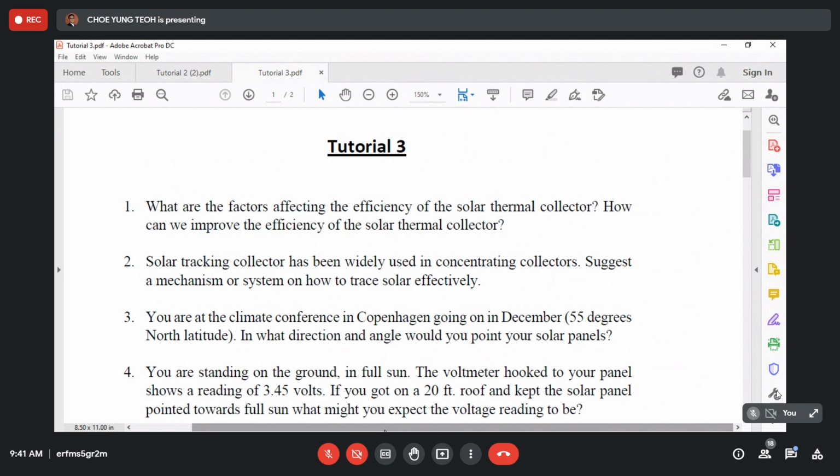But in terms of use in the evacuated tube, methanol is a very good idea. Okay, because it can change phase very fast at the lower temperature, which will carry the heat to the heat exchanger. But for the solar thermal flat plate collector, we normally won't use methanol because the heat capacity is lesser compared to water. Okay, but it has the anti-freezing characteristic. Of course, this is another advantage of methanol.